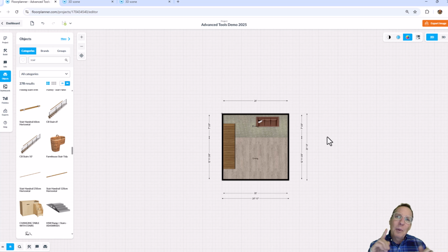So even if you have different partitions on your second floor, at least copy your structural members exactly in alignment to the second floor, and then just delete your peripheral partition walls and build from those stationary points. And then you'll be sure that everything's directly above and below each other.